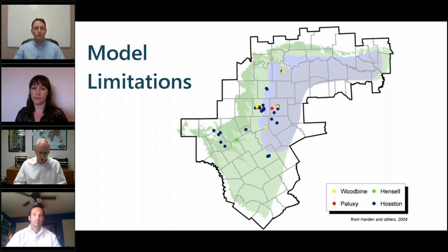The third thing is the limitation on how the models should be applied or used. It's important to remember that these are regional scale groundwater models. Large cell sizes, typically a mile by mile. They typically are operating on 1-year stress periods. It's also important to remember that these are, again, regional models. They are calibrated and evaluated regionally. Some areas within the model domain may perform better than other areas, and the model may still fall within a calibrated model.